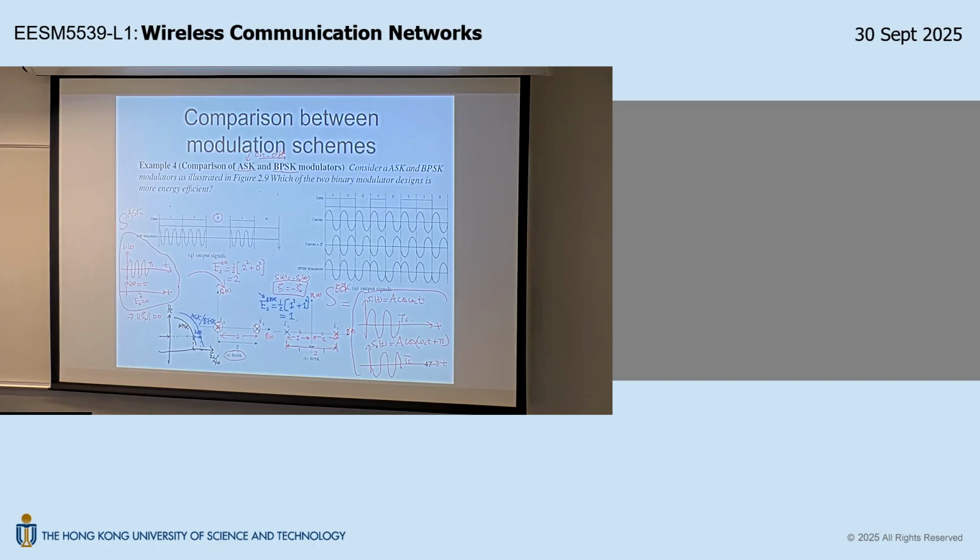Now, the next level. Remember when we talked about binary digital modulation, we said that there is one way to increase the bit rate without increasing bandwidth, right? So the bit rate is equal to this term times 1 over Ts, in bits per second. My analogy is that this term gives you the frequency of minibuses leaving the transmitter, and this term gives you the number of passengers per minibus. So these two together give you the bit rate, the number of passengers per second. And we explained that this term determines the bandwidth. So for a fixed bandwidth, you cannot change this term.